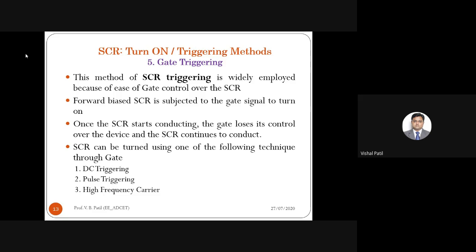आता मग गेट थ्रू टर्न ऑन करायचे असतील तर कुठल्या मेथड्स आहेत का, म्हणजे गेटच वापरायचा आहे, परंतु कुठल्या वेगवेगळ्या पद्धतीने तो आपण वापरू शकतो. डीसी ट्रिगरिंग, पल्स ट्रिगरिंग अँड हाय फ्रिक्वेन्सी ट्रिगरिंग, हाय फ्रिक्वेन्सी कॅरियर, या मेथडने आपण काय करू शकतो, डिव्हाइसला टर्न ऑन